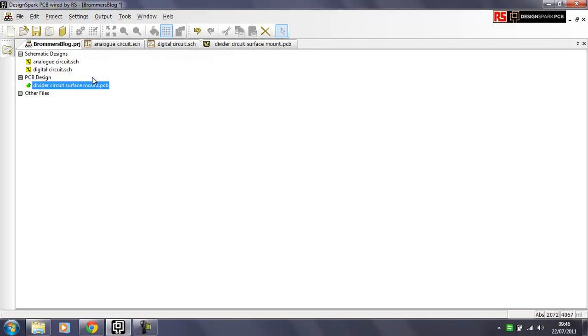Now some of the other important advantages of what this offers you is that when you have multiple schematic boards in a system, it allows you to use certain nets globally, basically. So maybe you have your 5-volt net, or some signal nets or such like. Because all these are contained underneath the project, it automatically compares between those and makes sure that there are no conflicts or duplications in your nets as you move across the boards.